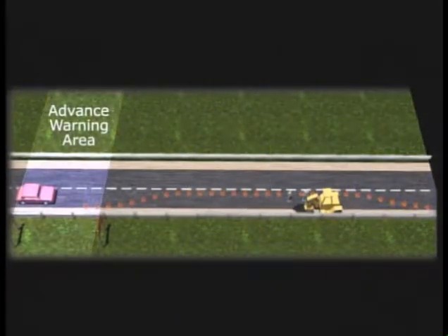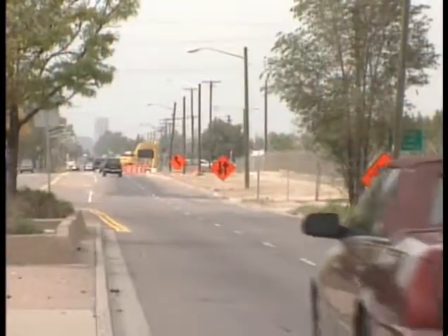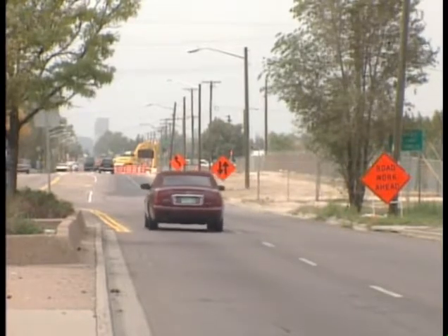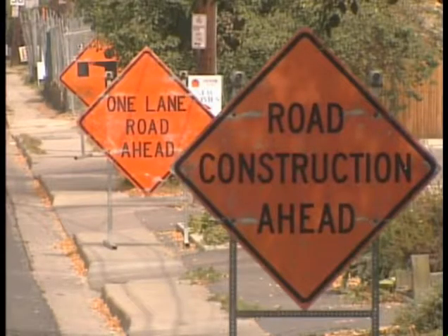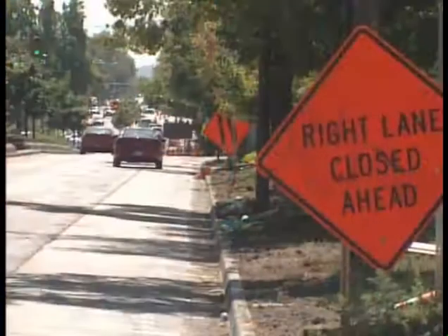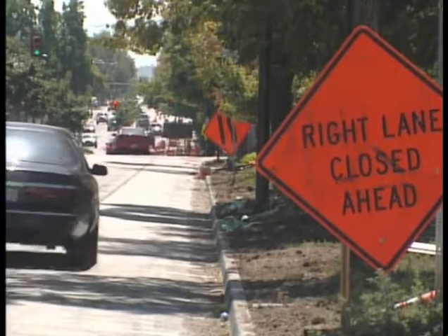The first zone is the advance warning area, where drivers get the first visual indications that they'll be encountering a work site. It's also where they should begin to slow down. A series of signs in this zone should let oncoming drivers know there's a project in front of them. Distances between the first sign and the transition zone will vary significantly depending on the speed of traffic or unique characteristics like curves and hills.